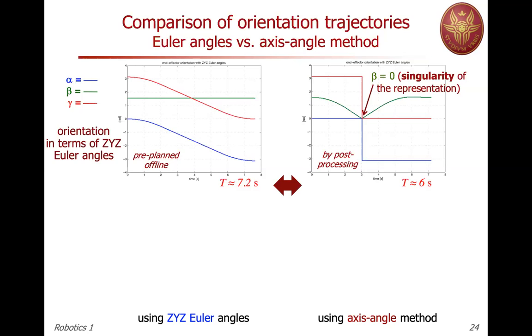You know, if the second angle is not rotating in a ZYZ or ZXZ or the other representations in which the first and the last axis are the same, when there's no rotation around the second axis, indeed, the first and last axis align, and this is a singularity because we don't span the whole three-dimensional space with the 3 axes of rotation. This should be clear at this stage. So we see that we would have encountered a singularity in that case.